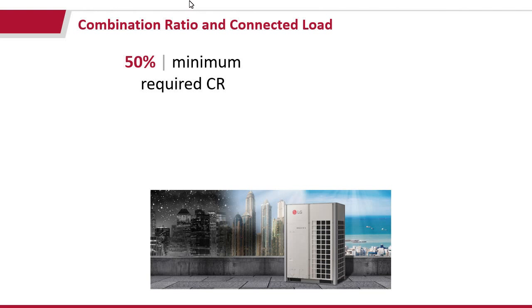Don't think, oh, I'm going to build this out later and put one small 2-ton unit on a 20-ton outdoor unit. It's not quite like chilled water, and refrigerant needs to be kept happy and within certain pressures and levels that it is comfortable operating in. Then 80% would be the minimum recommended. So if you wanted to leave a little extra space for the future, or if someone said, actually, I'm still a little bit hot and they want some extra capacity added, whatever the case is, then 80% would be the minimum that you'd want to leave as a little buffer.